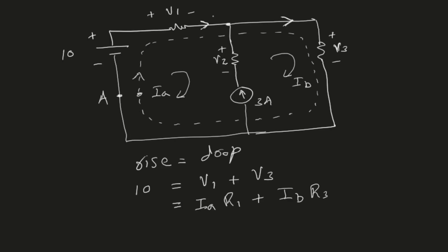Because if I say this is IC, then this is also IC. And this would mean that this branch is forbidden to take any current or produce any current. This branch is kind of now not present. It's not there, which is not the case. So therefore, that is wrong to do. So we cannot say that we have the same current in the two meshes.